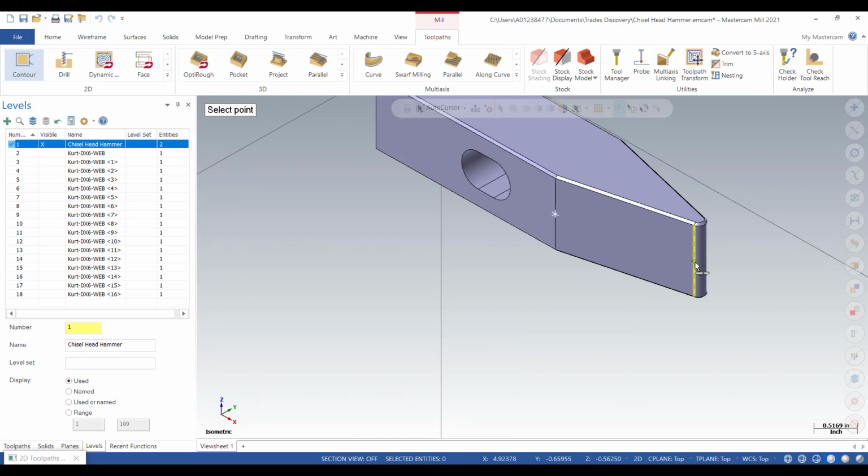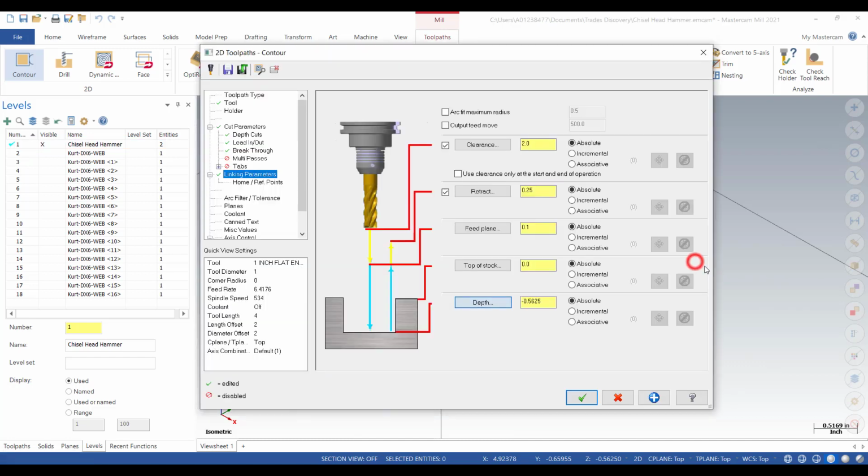Anywhere you can pick. You see it snapping on the midpoint. So once I click it, it picks up the depth automatically there. We can always write the number here. So make sure you're always typing the negative number if our 0 is on the top in this case. So it will be negative 0.562, right? So yeah, so you have both options. If we are working with solid model, we can actually use these buttons to pick up the numbers rather than entering it manually.